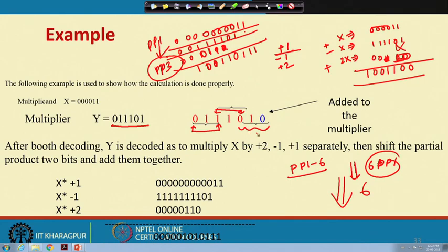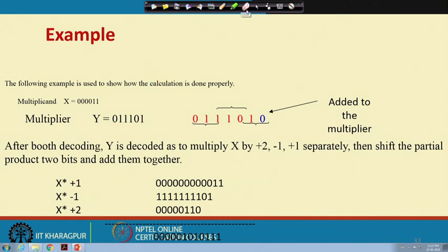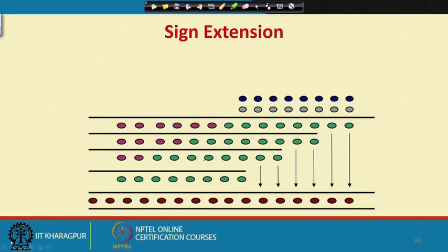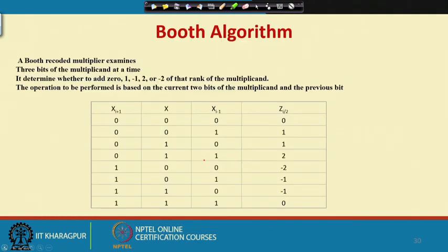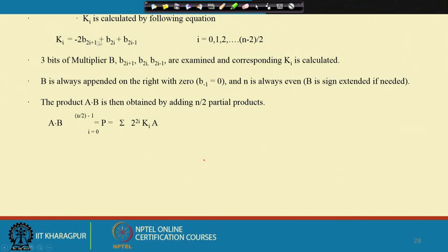Okay. So, this is the technique for Booth's multiplication. Here we are considering radix 4, that is why we are considering something like this. If you want to change the radix, you can consider more bits, 4 bits, and at that time, where will be the change? There will be a change in this particular location. So, we will consider more of Booth's algorithm, and if I change the radix, what will happen?